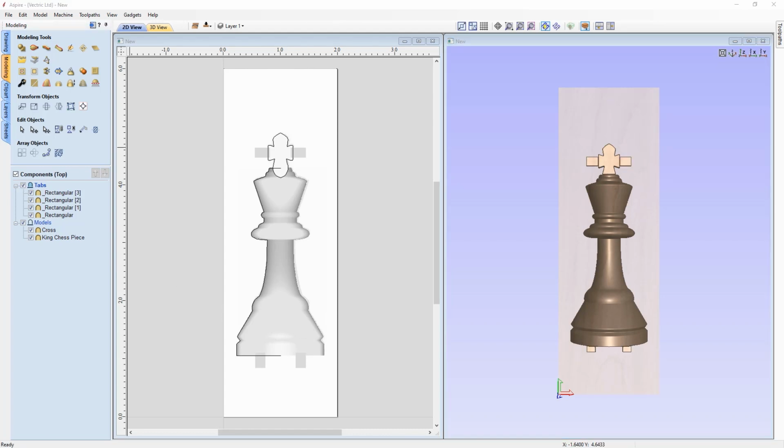To keep the material aligned in the X, Y, when we flip the material over, I'm going to look at using the non-symmetrical dowel hole method. This is where we would drill holes partially through the top side of our material, and then in the software we would copy the dowel positions from the top side over to the bottom side. We will cut the holes for the bottom side directly into the spoil board, allowing us to have perfect alignment in the XY when we flip the material block over and push it onto the dowels. Now there are many other methods that we could use, but I know this method is fail-safe because there's only one way our material will fit when we flip it over.